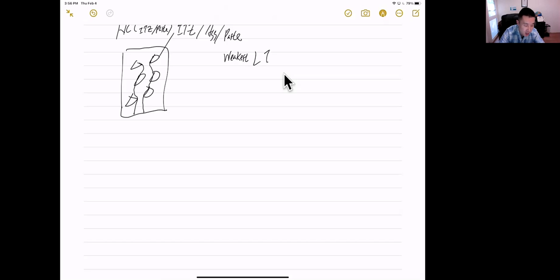Okay. So for normal concrete, if we increase the strength of aggregate, it does not really help, because aggregate is already the strongest part. You increase the strongest, you didn't enhance the weakest link, so the strength will remain almost the same.